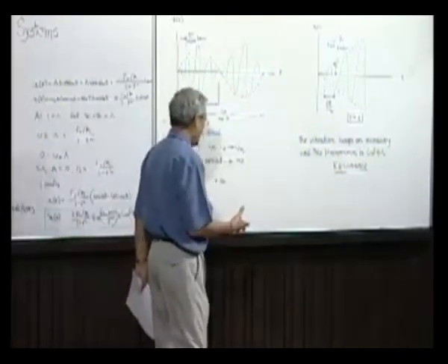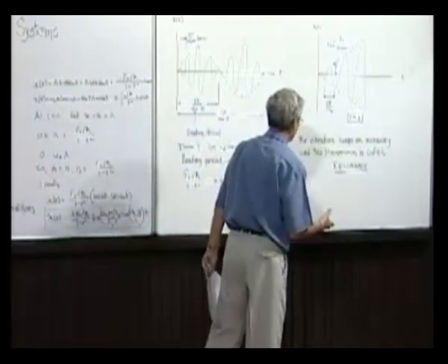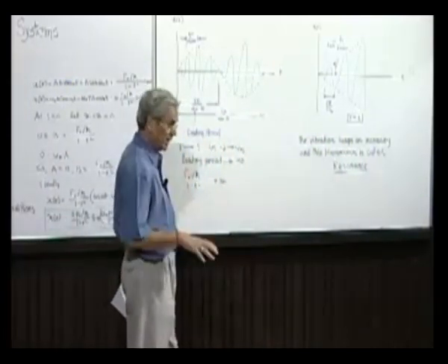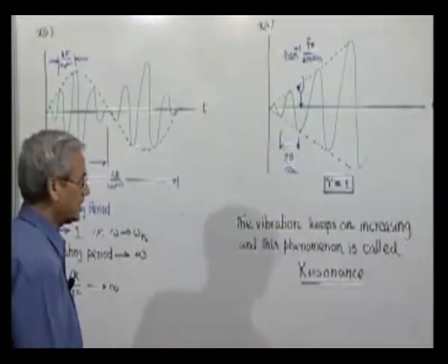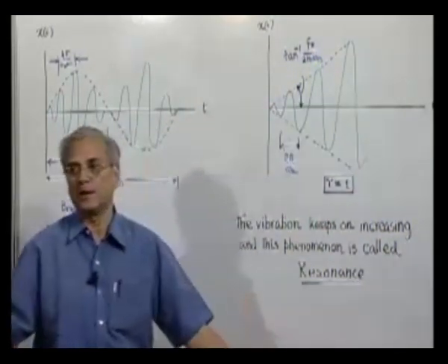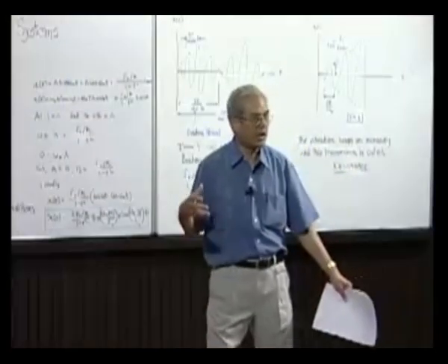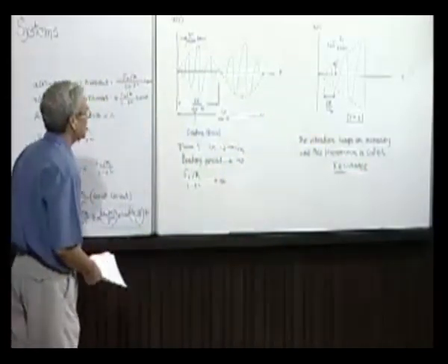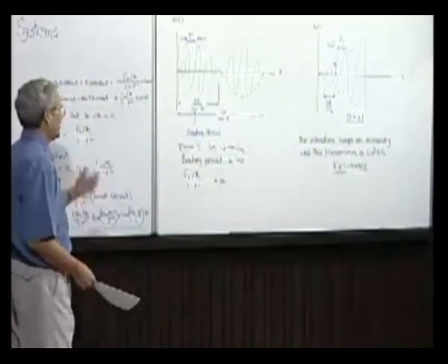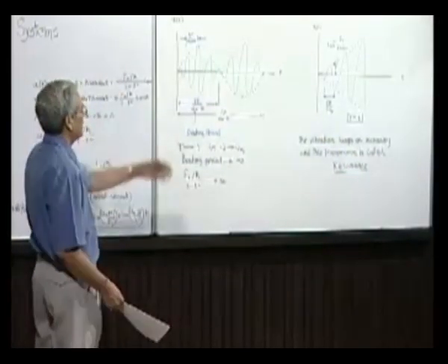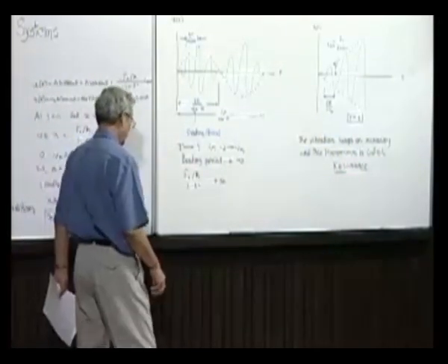But the common view sometimes held is that if resonance takes place, the amplitude of vibration is infinity. It is not so. Actually, what happens in resonance is that the intensity of vibration keeps on increasing indefinitely. If you allow infinite time, and if the system is capable of taking infinite deformation, it will go to infinity. But really what happens is that the system gets damaged because of the large scale oscillations taking place.